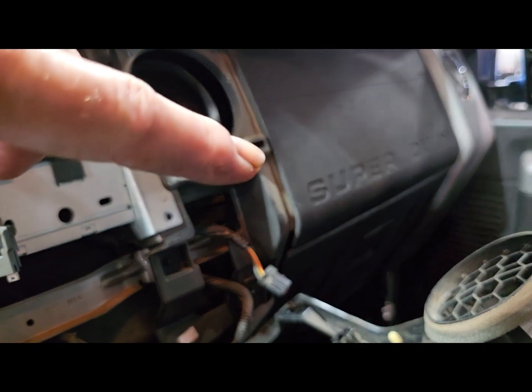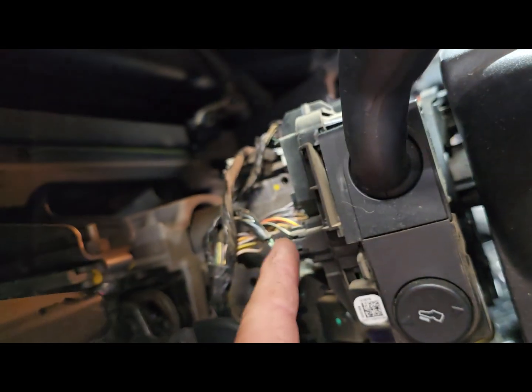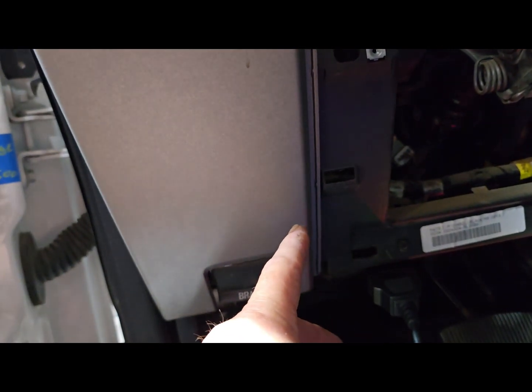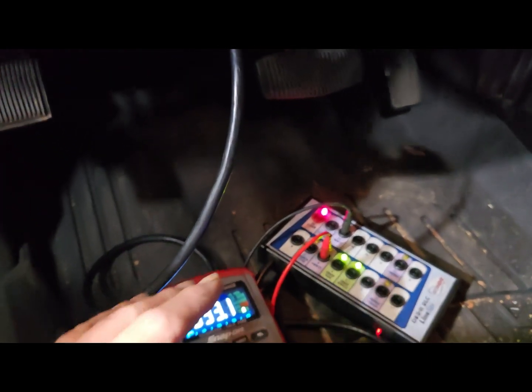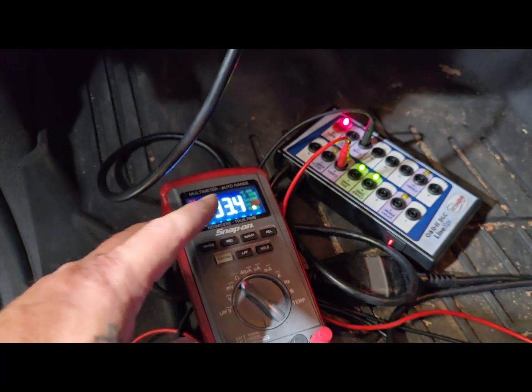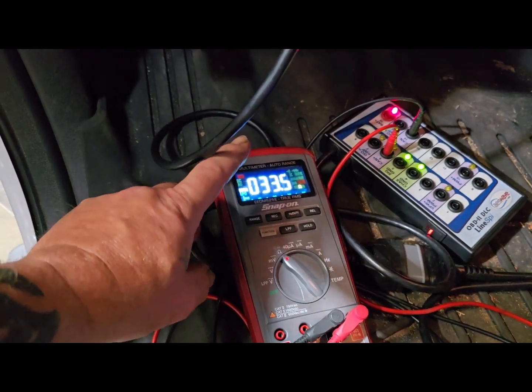However, I'll talk about that in a second. I have disconnected the steering control module. I have disconnected the parking aid module under the dash. And I tried the ABS before, but that was before when it was here. I did some quick tests, and then he had to bring it back this week. So now I'm going to figure out why we only have 33 ohms, and we're supposed to have 60.